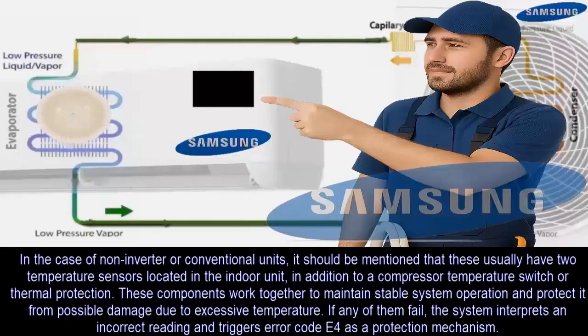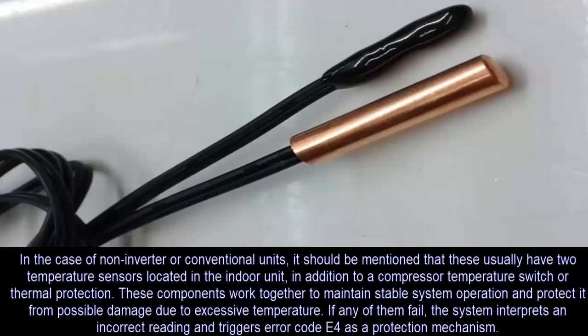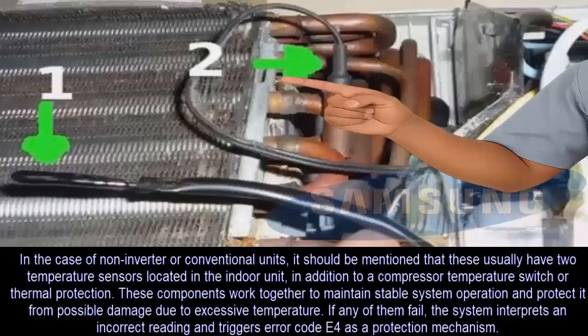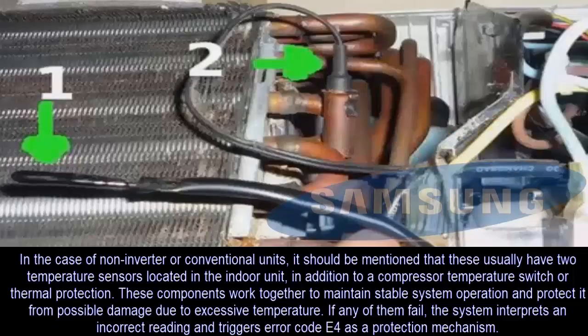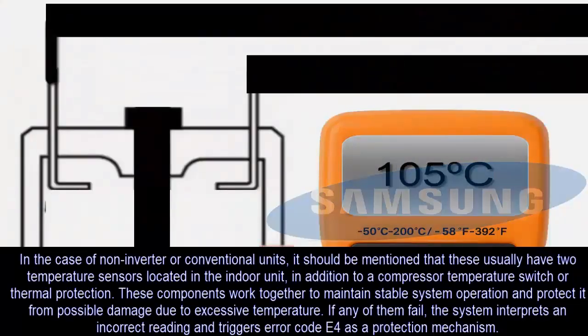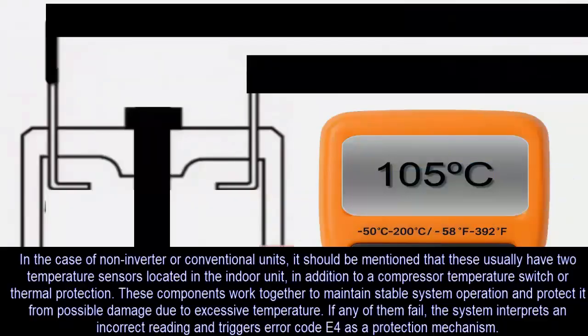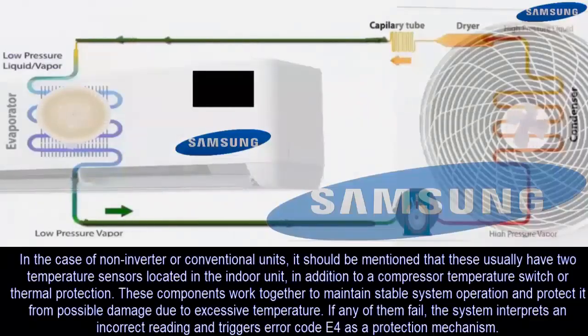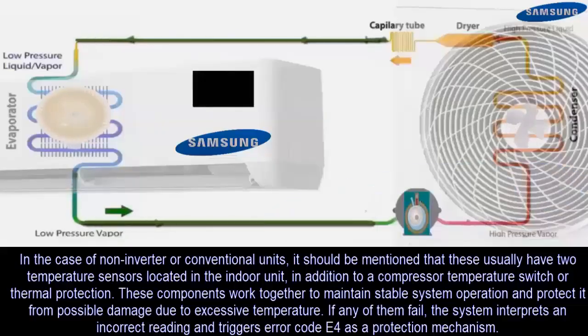In the case of non-inverter or conventional units, it should be mentioned that they generally have two temperature sensors located in the indoor unit, in addition to a temperature switch or thermal protection for the compressor. These components work together to keep the system operating stably and protect it from possible overheating damage. If any of them fails, the system interprets an incorrect reading and activates the E4 error code as a protection mechanism.